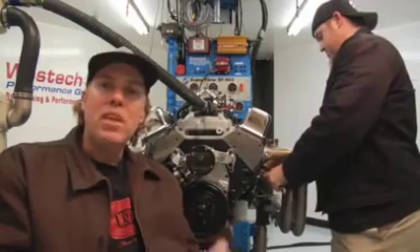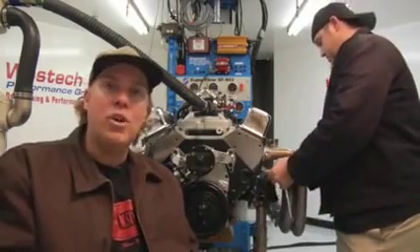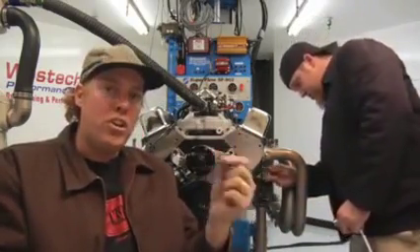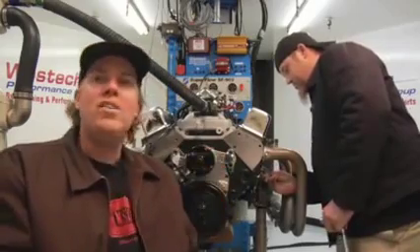But in truth, that spark happens a few degrees before the power stroke, at the end of the compression stroke. In other words, right as the piston is coming up for compression, just before it reaches top dead center, or TDC, the spark plug fires. That distance before top dead center is what is known as ignition timing.